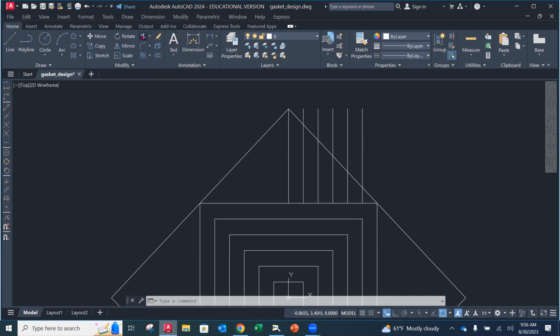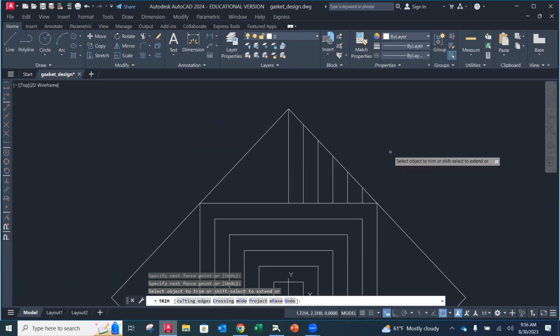So I'm going to go up to my trim command, left click, drag across and then release to get rid of all those, or separately do them. It's up to you. You can do the tops where you want to get rid of. Now I'm going to take this and mirror this on the other side, so it saves me the extra offsets and the extra trim. So I'm going to escape because it wants to keep going here. Notice I have that box by my cursor, back to my normal cursor.